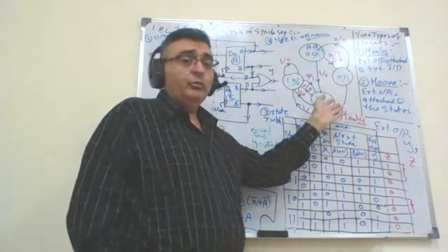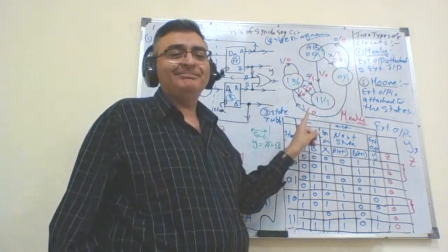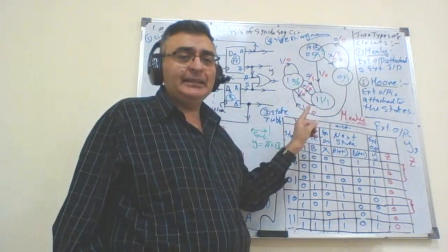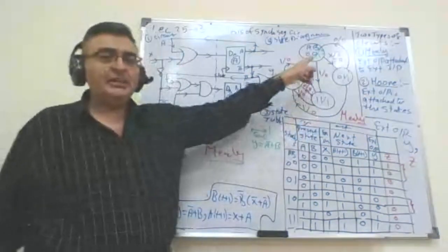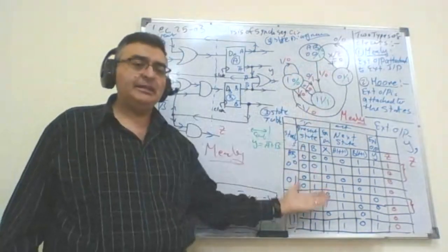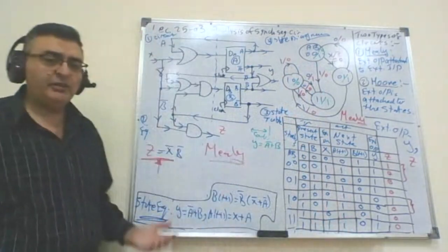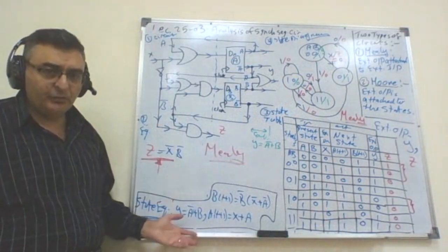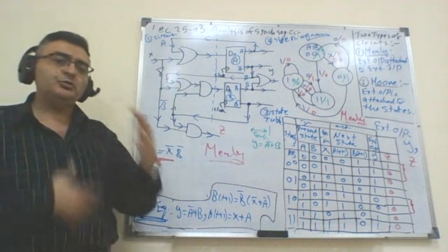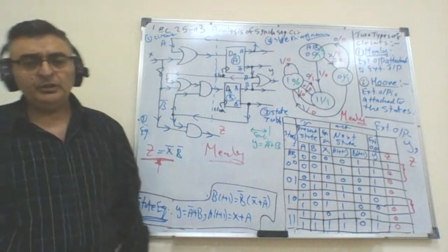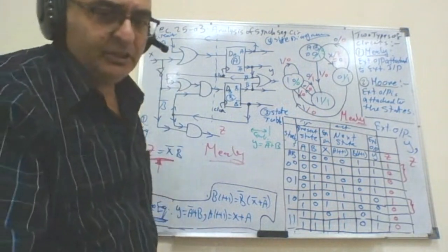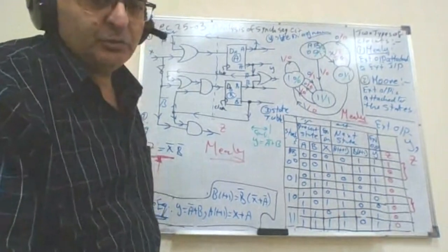In the design, we will start by building the state diagram for the problem. From the state diagram, we will be able to get the state table. We will go retrograde. From the state table, we can derive the state equations. And from the equations, we can draw the circuit, so to design the circuit. See you in lecture number 26, synchronous sequential circuit design.